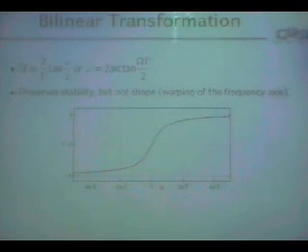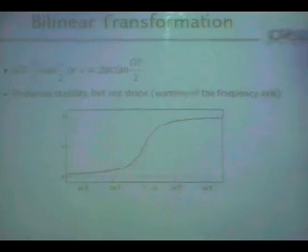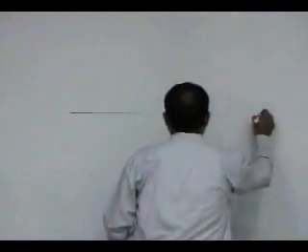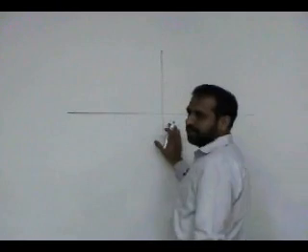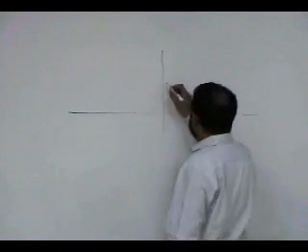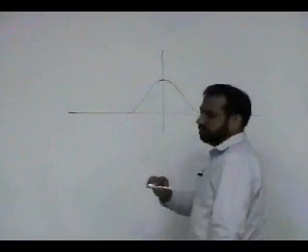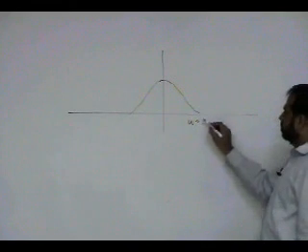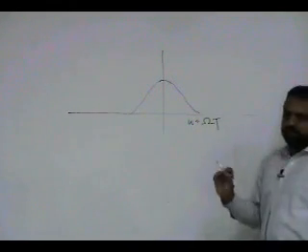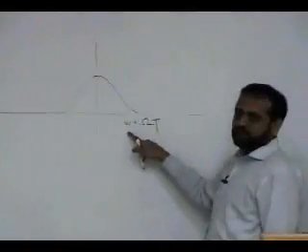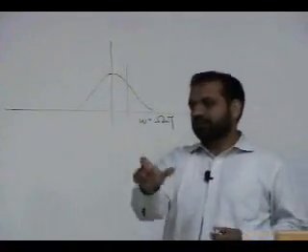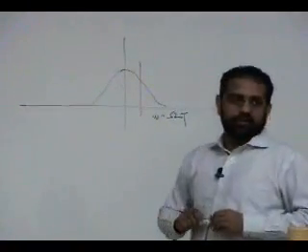The problem with the impulse invariance method is that it is a linear transformation. Linear means that you are only linearly scaling the frequency axis. Whatever your frequency response is, you are creating a small omega which is equal to capital omega times T. It's not doing anything else. But once you have this omega, then at every 2 pi, wherever that 2 pi occurs, you have to make a copy of it. So that copying is basically causing all the problems.